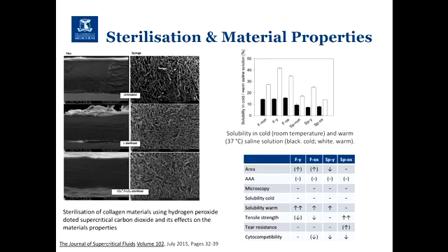So this is one where they are sterilising collagen. The three different techniques that I told you about, whether or not they were good or problematic for polymers, I usually refer to synthetic polymers, metals or ceramics. A lot of the materials these days are more biological. So with collagen, you can't do gamma radiation, you can't do steam.